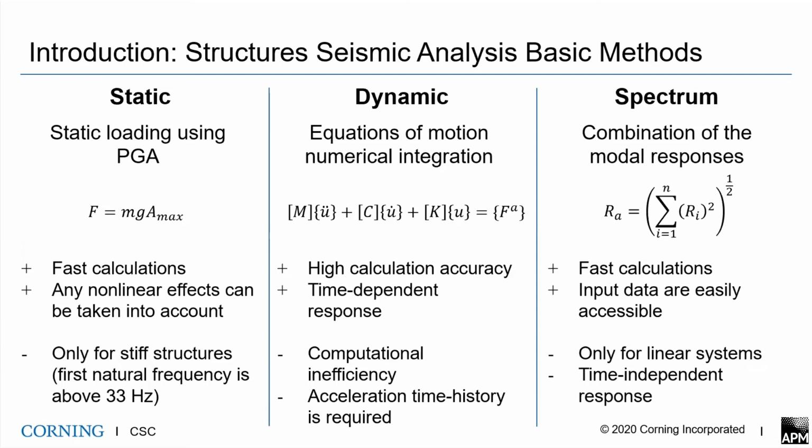But this type of analysis requires significant computational resources, because the integration time step should be small enough to resolve the highest frequency in the earthquake accelerogram. The modal superposition transient method is much more computationally efficient, but it can be applied only for linear models.